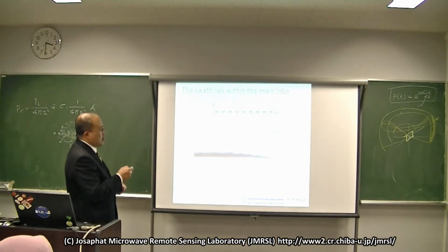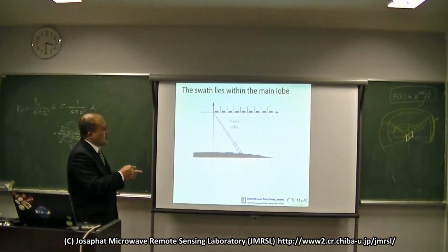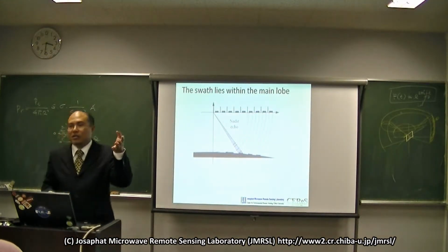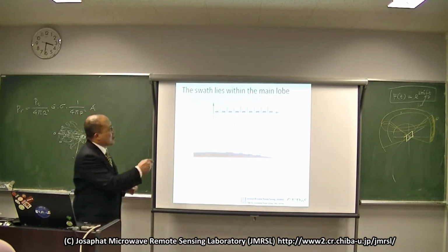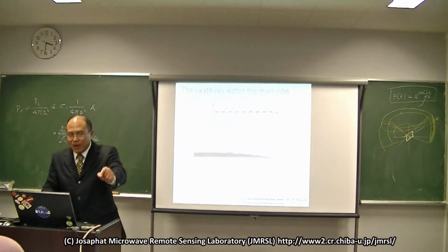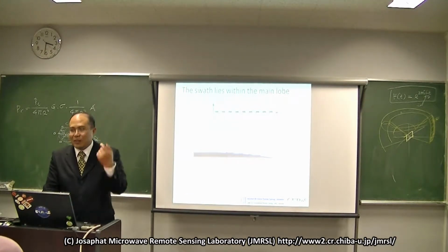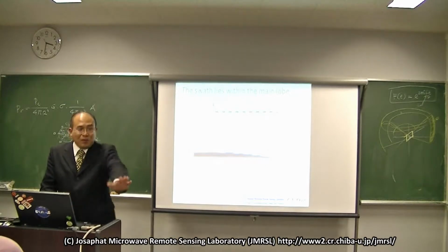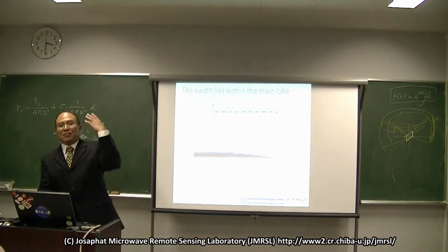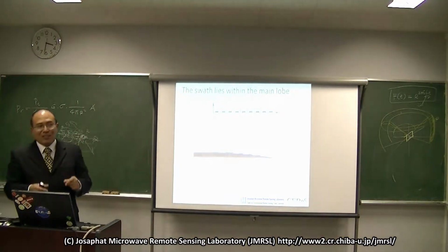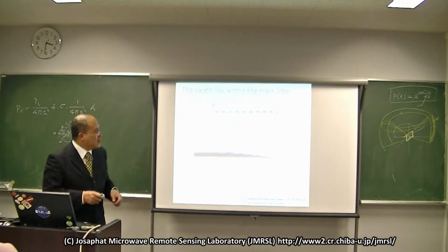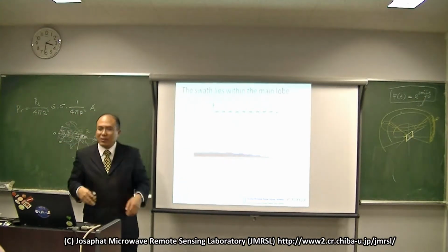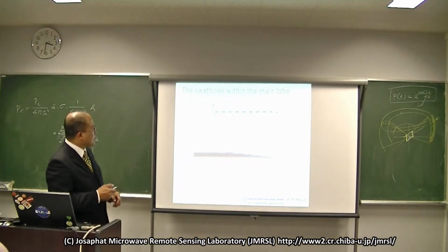Okay. Actually, when we transmit in spaceborne, we transmit and suddenly it does not come. We need to wait maybe some seconds, and finally it comes. But if the UAV is very close, even if you have not yet finished transmitting, it has already come. So you must calculate when to transmit and when to receive. If not, there is a collision.